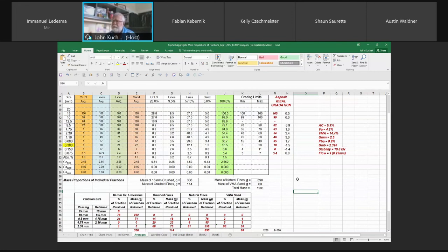Well, again, remember what we said? If you're designing for a 42 MPa mix, you got to have that standard deviation. So you're going to be probably designing for 46 or 47. So now they're getting higher again. They're saying, wow, our concrete is way too brittle. Well, yeah.